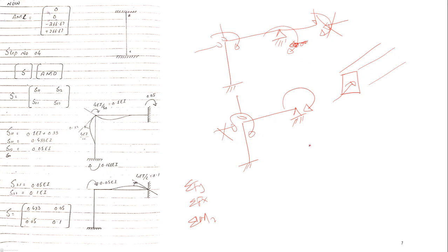Similarly, for this column, the axial deformation is very small, so you can ignore this. So I have got 2 degrees of freedom, D1 and D2. So we have got D1 and D2 only. Rest it is easy. For fixed end load, this is WL. This is like ADL, or action due to load.